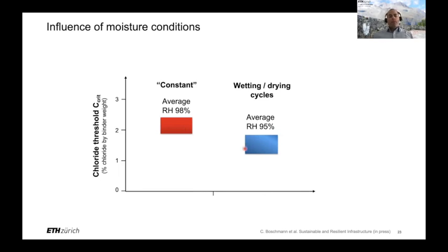Let me say one more word on this. It is generally assumed that this has something to do with the presence of moisture in the concrete, but I would like to mention here that even under these constantly immersed conditions, the electrochemical potentials of the steel indicated no oxygen depletion over the experimental time, which was several months, but suggested that we have still enough oxygen here in that case, and comparable oxygen concentrations, at least between those two series of tests.